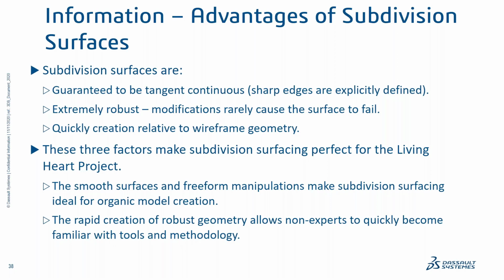We've seen quite a bit of improvement once we get to meshing off of subdivision surfacing that we haven't really seen before from a lot of the other reverse engineering techniques, like network of curves and things like that. These subdivision surfaces, just by their design of how they're formulated, pretty much always guarantee at least tangent continuity and usually curvature continuity. And those produce very high quality FE meshes just automatically whenever you do a modification. So those were the key ones that we've used.